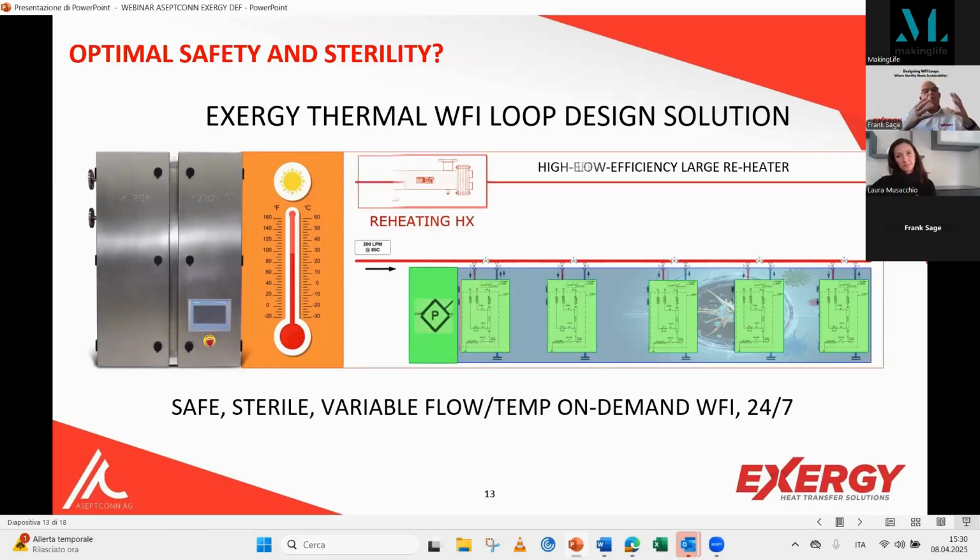So whenever offline heat exchangers are chosen, they can take 8 to 10 minutes before you can have the cold WFI. Our systems, as you'll see in a few moments, can do this in approximately 30 seconds. We can maintain full sterility all the way to the process equipment itself with no sterilization downtime, and we can reduce significantly the amount of instrumentation needed to ensure the sterility of ambient WFI distribution, and indeed the additional sanitization steps that are taken there.